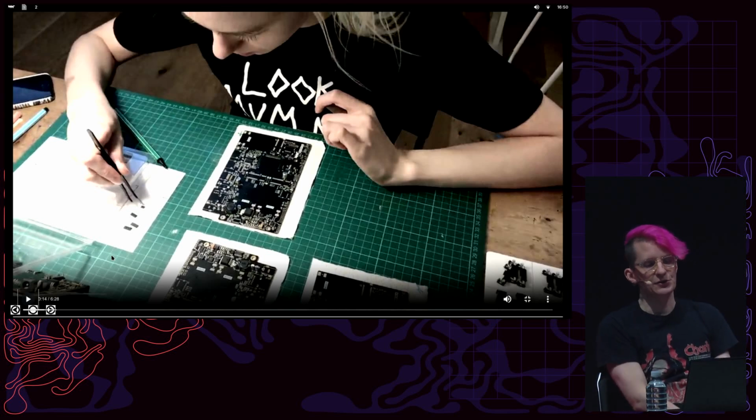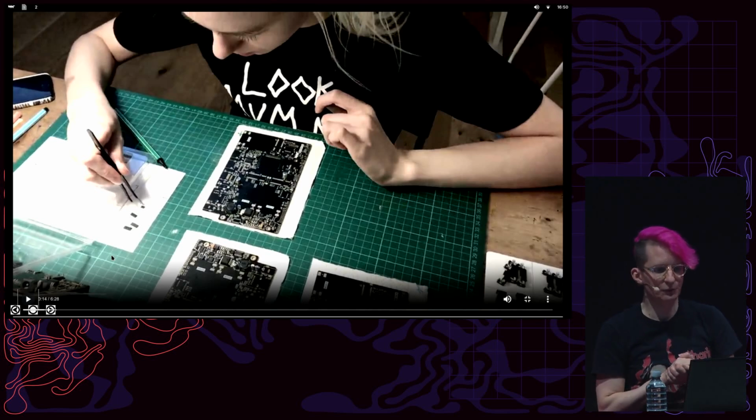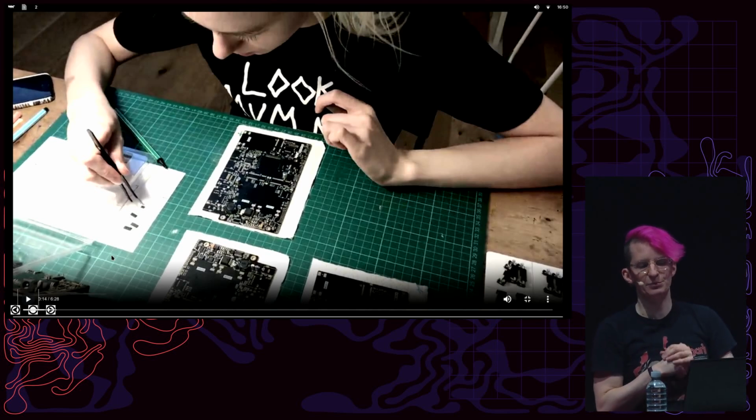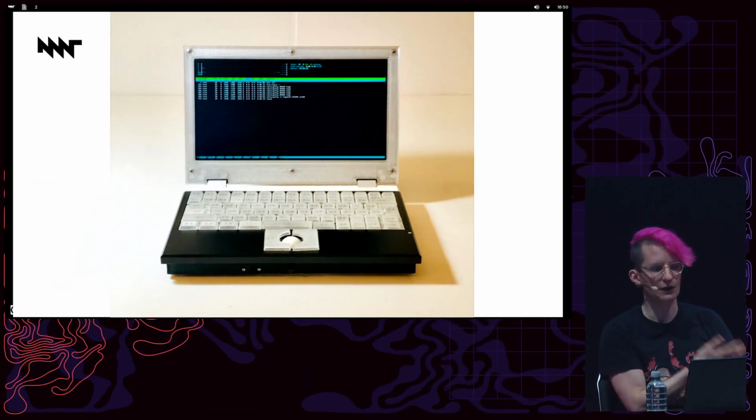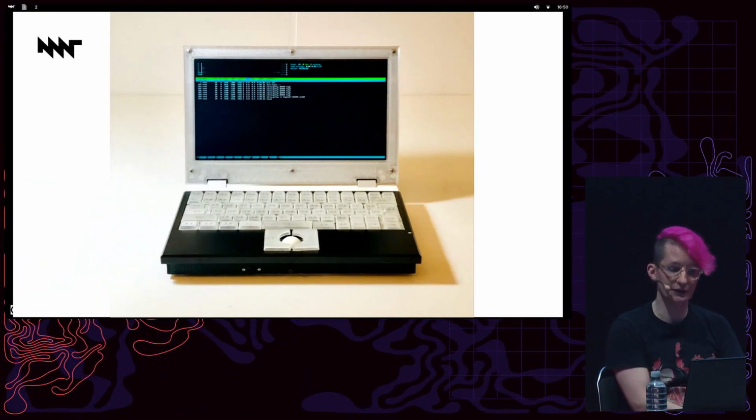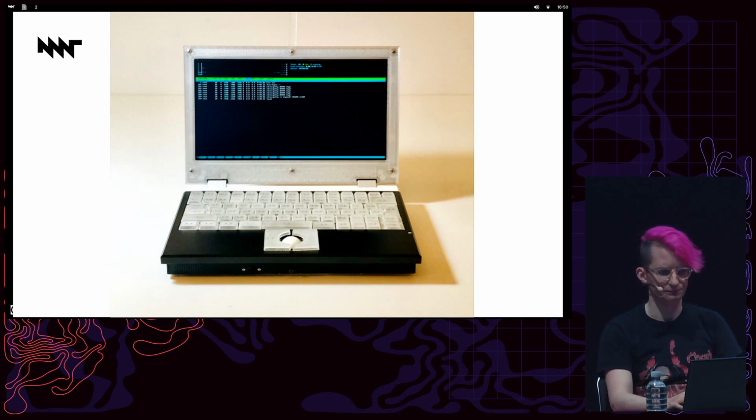We were torn about the manufacturing of the case parts. We really wanted to have a method that could be reproduced by anyone, but weren't satisfied with the slowness and imprecision that 3D printing had back then. Anna set up a temporary lab at the University of the Arts in Berlin for, I think, several months to try if she could vacuum cast the parts, but although promising, the results were unsatisfying, with lots of bubbles or broken corners. So that was the point where I decided to try aluminum CNC milling and actually outsource that part to a relatively small company in China, JPR. We still work with them today on all the laptop cases.